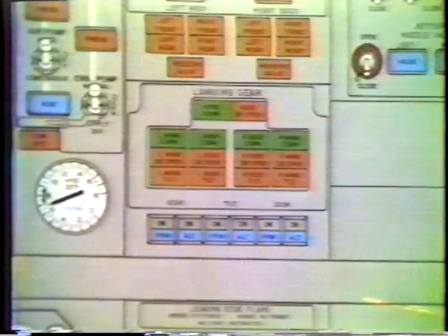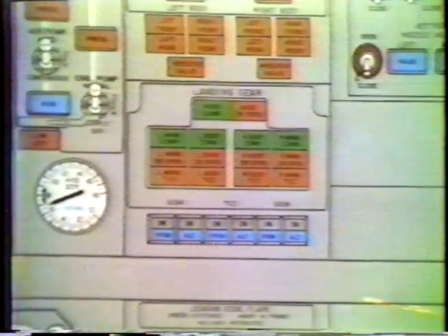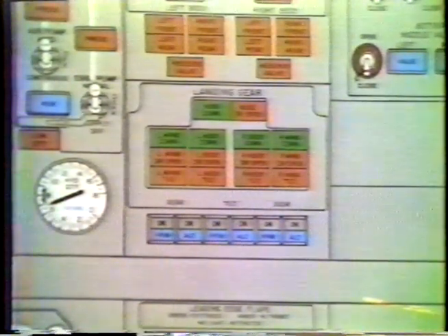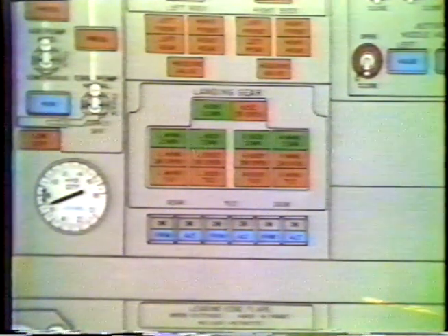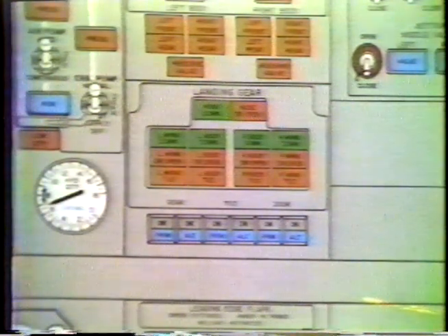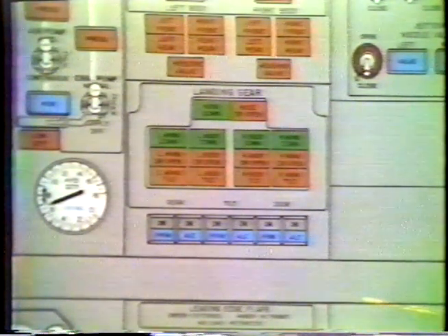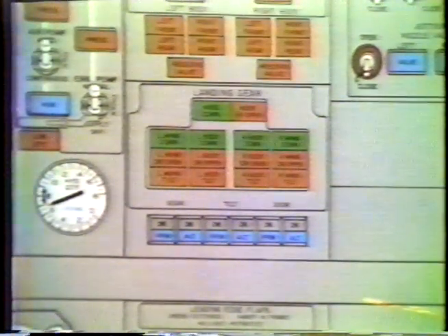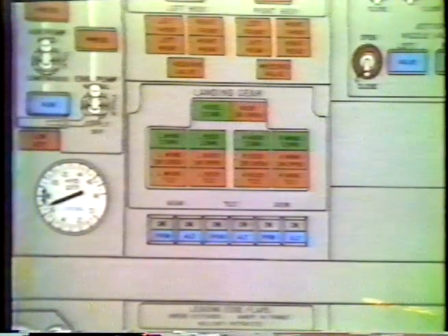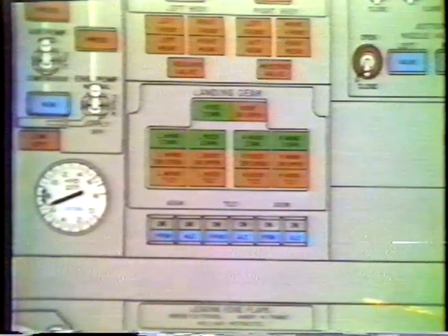actually going up or going down and locking. Because of the gear sequence valve, the door must first come open for the gear to move. Then the gear has to be in a locked position before hydraulic fluid is available for the door to close.